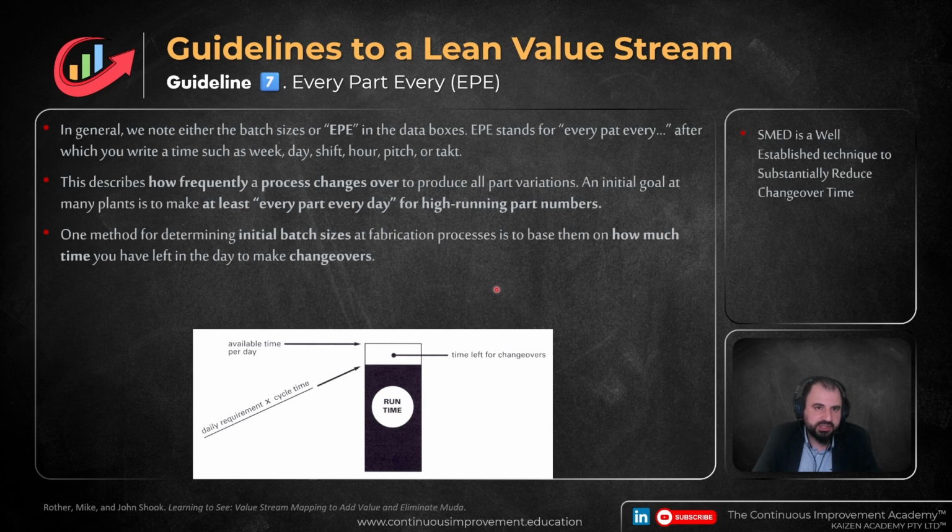And by shortening this time, upstream processes can respond much faster to downstream needs, requiring even less inventory in their supermarkets. So there are very well-known inspiring stories from Toyota where they had, in their chassis, a changeover time of 3 days, and they managed to reduce it to 11 minutes, which allowed them to be more responsive and more agile.